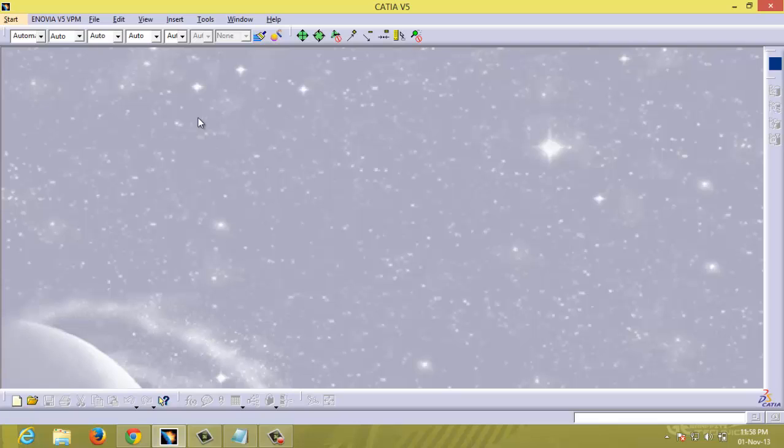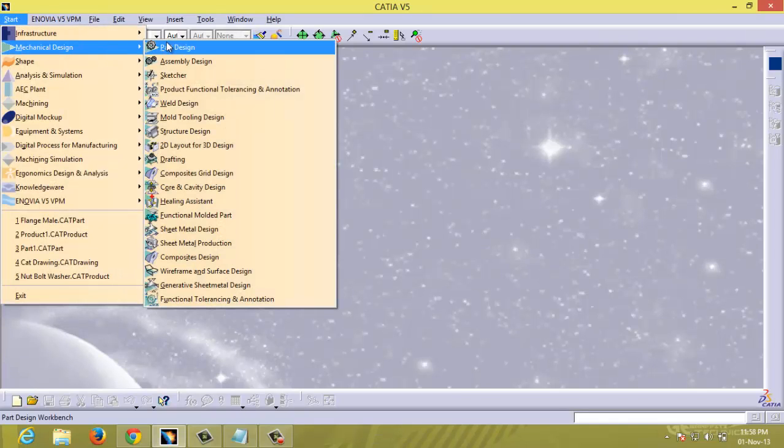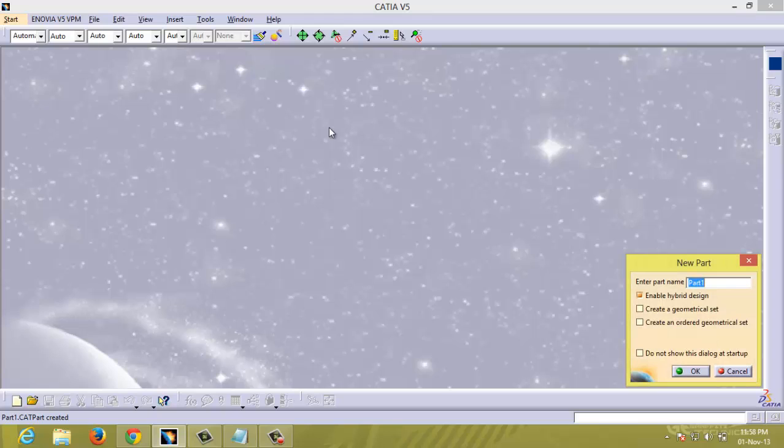Then the rocker length is the default one, and it is 100 millimeters, and the distance between the first and third link, that means the length of our fourth link, is found to be 189.277 millimeters. So we can go to the Part workbench to create the links.